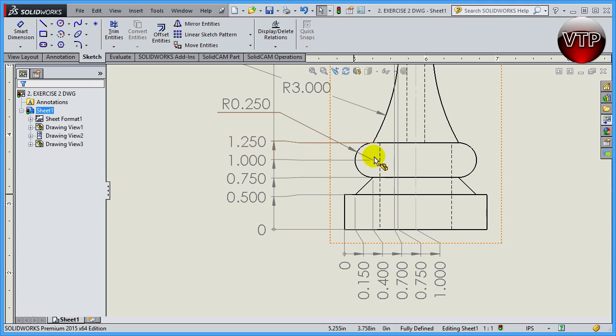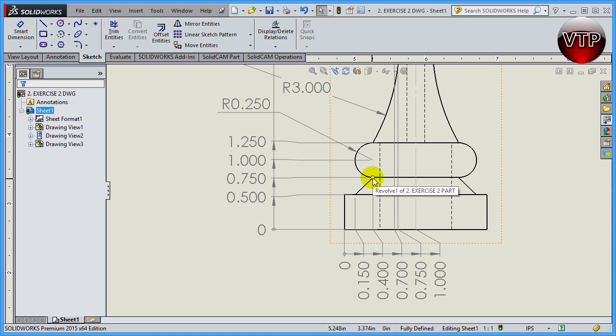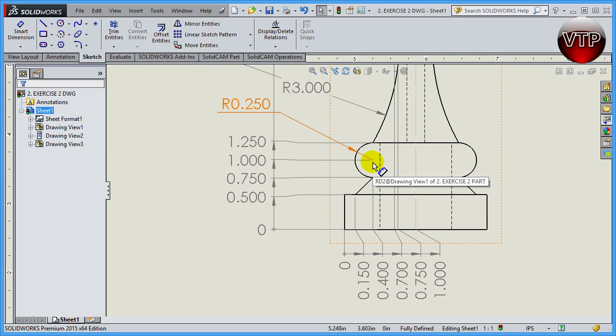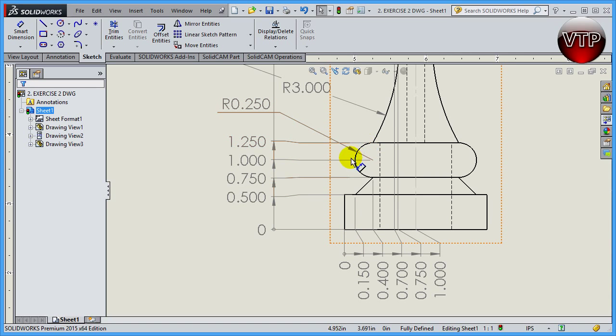So now we want to create this line right here. Now there's multiple ways you could do this. You can actually create a line from here to here and state that it is a 45-degree line, or you can create your circle, if you know the exact location of that circle, and then connect it by that line. So that's the best way that I would do it. I already know that there's a circle over here, and I know its midway point. You can connect it to this line.